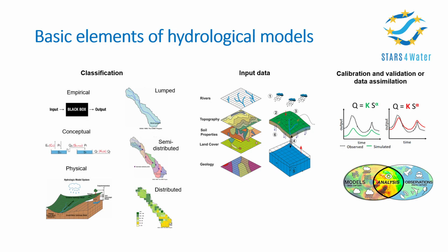The accuracy of those models can be improved by using two different approaches, such as calibration and data assimilation. A calibration process is performed by tuning parameters to match historical data, like river flow. However, for purely physical models, data assimilation is performed, which is a common process that continuously updates the model's internal states, like soil moisture or snowpack, by integrating satellite information and in situ observations.